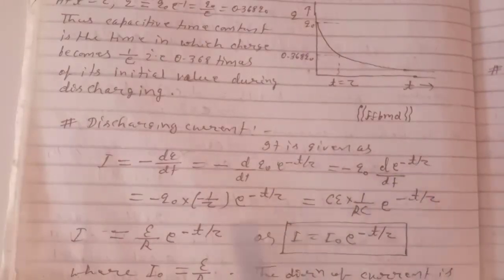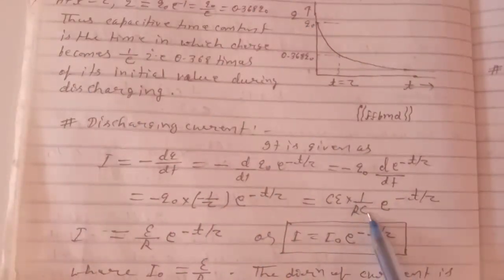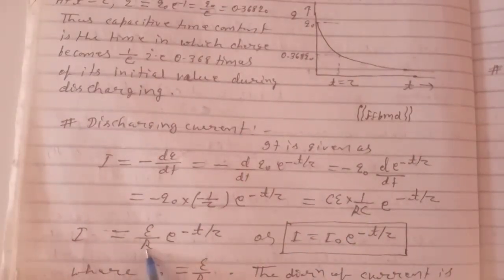Now the differentiation of this will be minus q naught into minus 1 by tau into e to the power minus t by tau, equals, with q naught equal to CE, C into 1 by RC e to the power minus t by tau. C will cancel out, so I equals E by R e to the power minus t by tau, or I equals I naught, that is the initial current, e to the power minus t by tau,